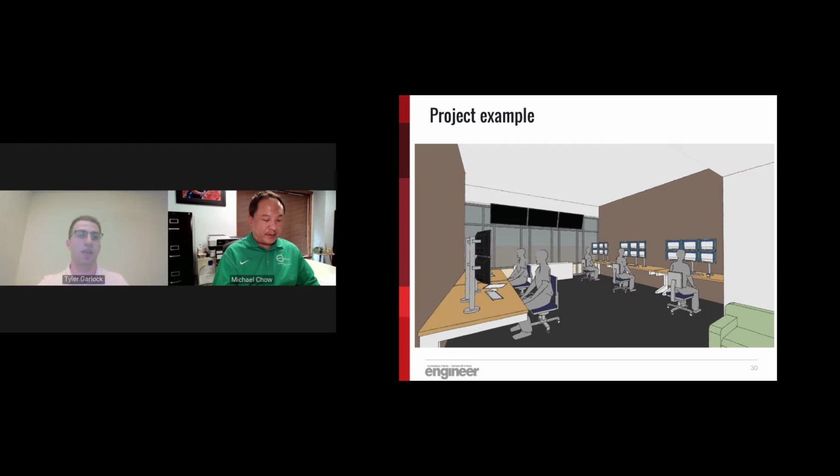Moving on. And then the next question is, people are working in these spaces for 12 hours at a time. Doctors work long shifts, more often than not. So then it became comfort for the people working in these spaces. The original design was to have dark walls behind these monitors. Well, it doesn't matter how much vertical light I put on those walls, you're going to be struggling with getting light onto the faces because dark walls absorb light.